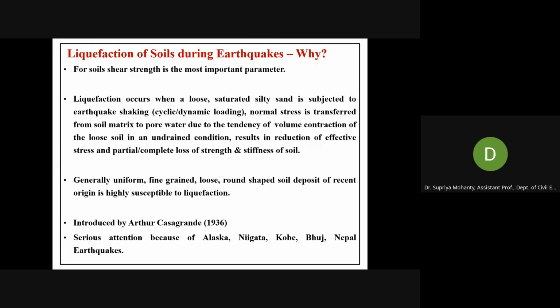In that case, there may be chances of pore water pressure increase, and when it matches the total stress, the effective stress becomes zero. So when is there a chance of increase in pore pressure? The condition is if you have an undrained boundary, like a hard stratum or rocky strata below at your soil site, then there is less drainage path. Under that condition, if there is shaking or any vibration or dynamic loading, then under this ground vibration there will be a chance of increasing pore water pressure.